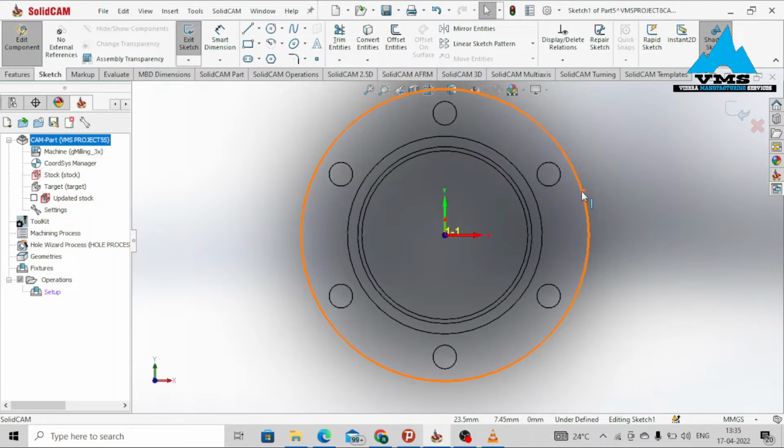You have to understand that when you are working with a CNC machine, you have to put extra material. This extra material is actually used for clamping, because remember that when you are working with a CNC machine, you have to clamp the workpiece using fixtures. Second point, when you are using extra material, it can also be used for surface finishing, especially when you are using a surfacing operation. Hope you got that.